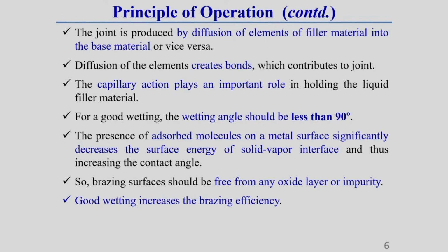Now, what is the diffusion process? That is very well known to you. Generally it is the movement of a substance from an area of high concentration to a region of lower concentration. I am not going into details about the diffusion process. Diffusion is driven by a gradient in concentration. Here a liquid and solid type of diffusion is going on, liquid filler wire and solid base metal. Due to this diffusion, the bonding is created and the joining is done.